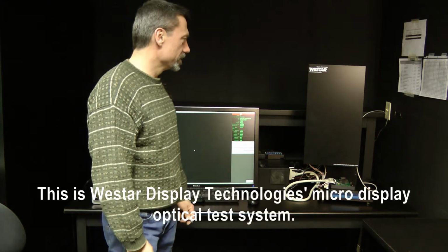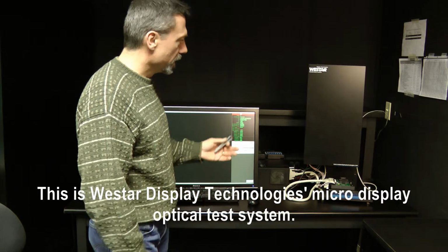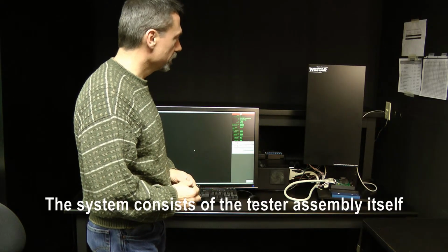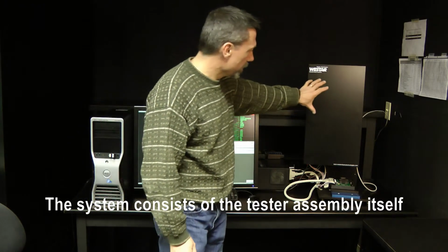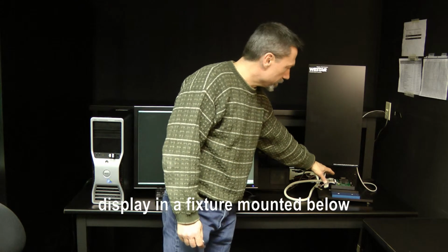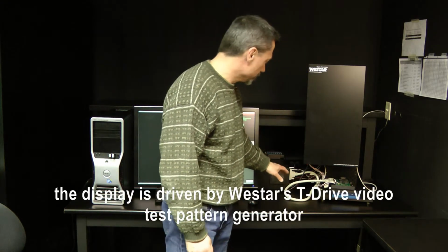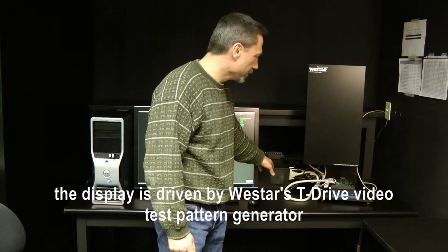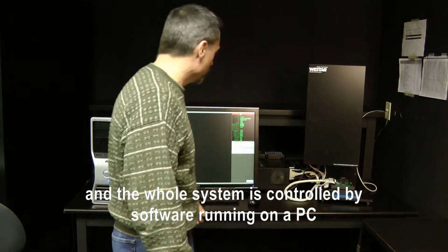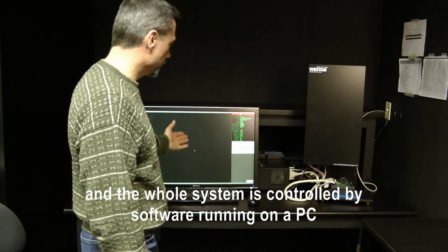This is Westar's Display Technologies Microdisplay Optical Test System. It's used for testing liquid crystalline silicon microdisplays. The system consists of the tester assembly itself, display in a fixture mounted below. The display is driven by Westar's T-Drive video test pattern generator, and the whole system is controlled by software running on a PC.